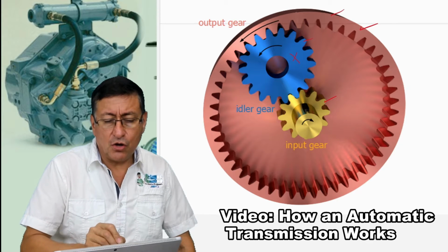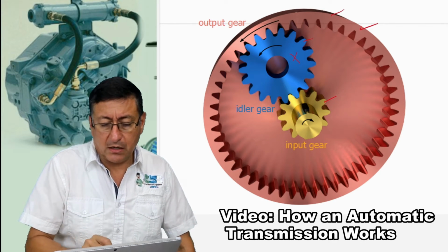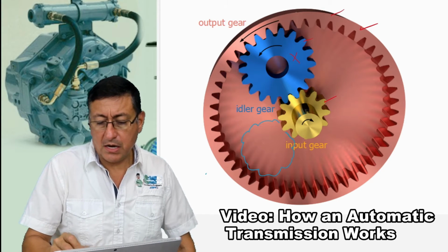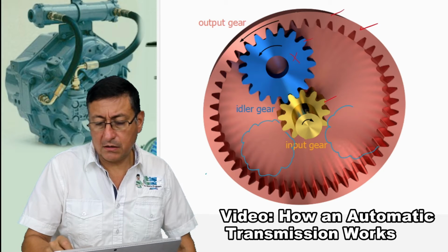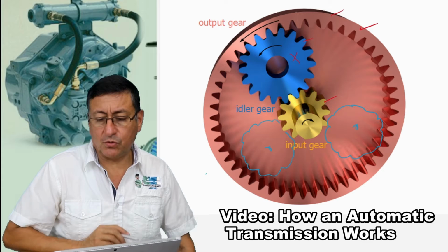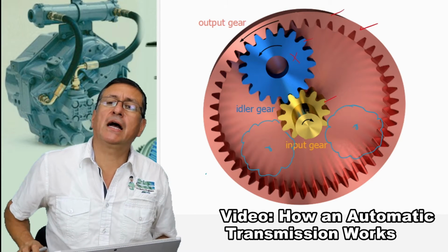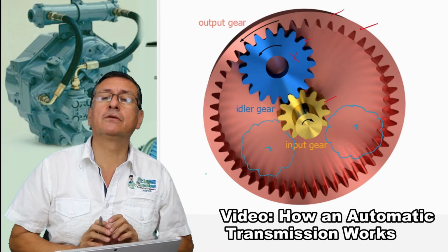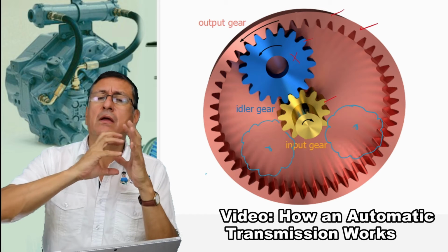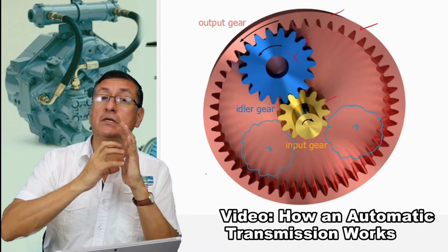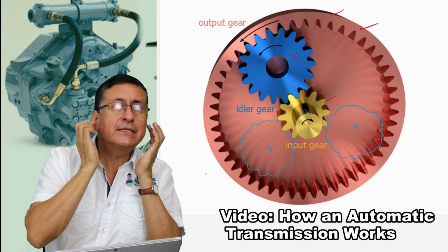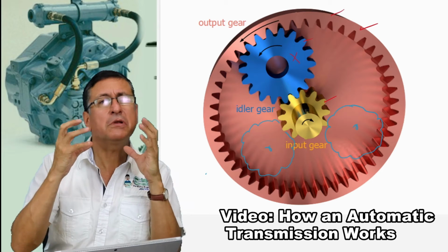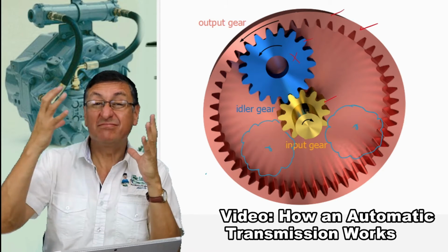Because in some cases you can design that system, no, with one gear, probably with 3 gears, other one here and other one over there, separated 120 degrees, and you have 3 gears. And this is a planetary system with 3 planets. There are planetary systems with 4 planets. What is the advantage? If you have more planets, it's more accurate, less sound, more precision. With 3, the sound is a little higher. With 2, is higher sound.